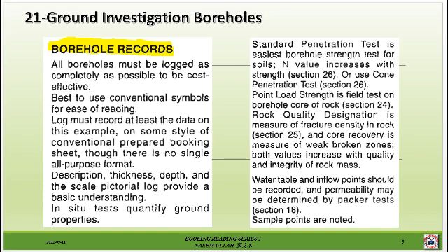In situ tests quantify ground properties. The standard penetration test is the easiest borehole strength test for soils. N value increases with strength. We will further discuss this in section 26. Or use the cone penetration test. This also we will discuss in section 26.